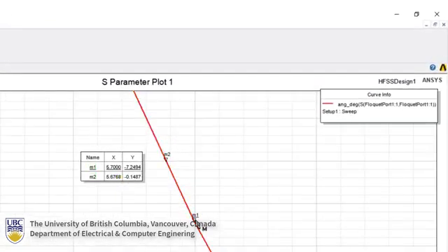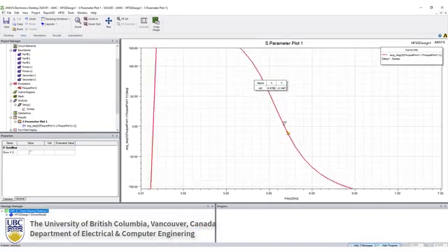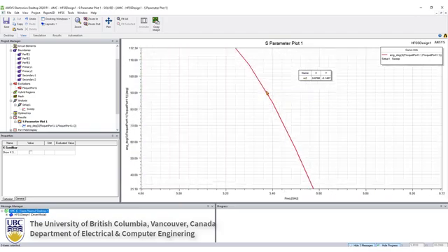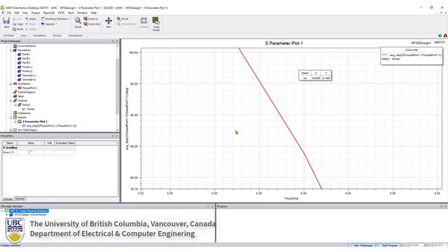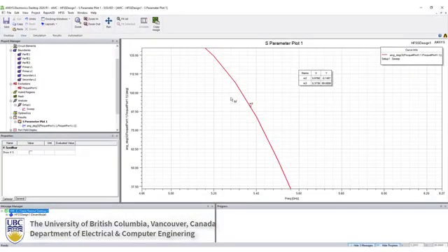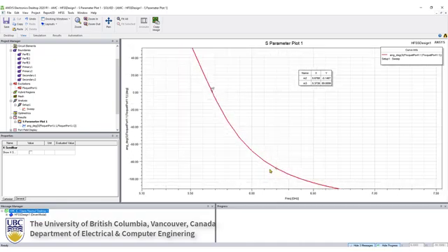I can delete this M1. So this is the resonance frequency occurring right at 0 degree, 5.67 gigahertz. And as for the bandwidth, we need to take 2 points, plus 90 and minus 90 degree. So this is our positive 90 degree, I think, this point. Let's define a marker. 5.3, this is our F1, and for the negative 90 degree, it would be somewhere here.